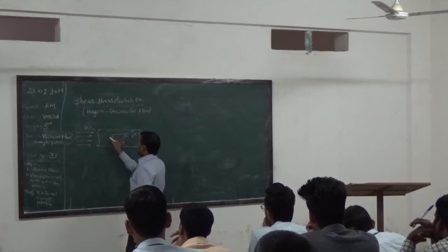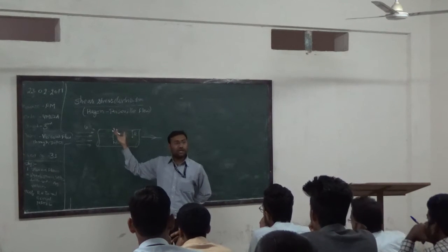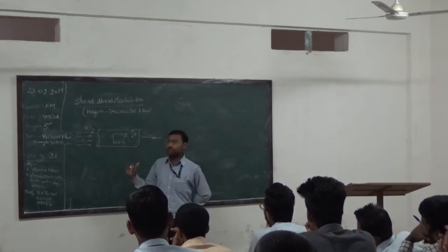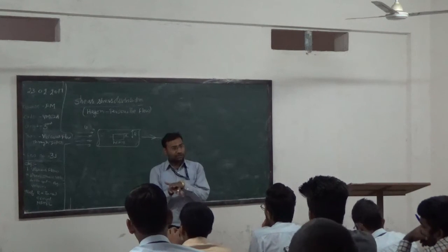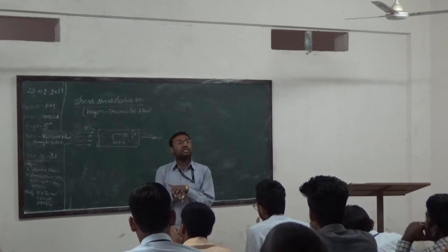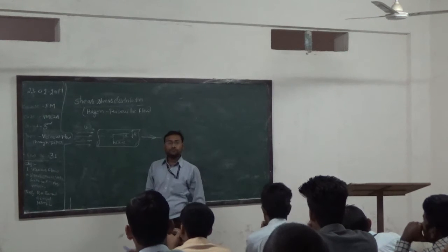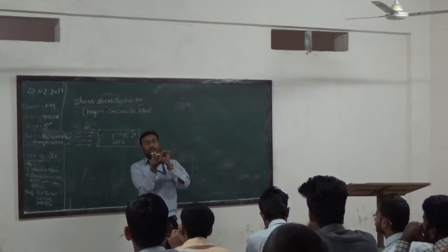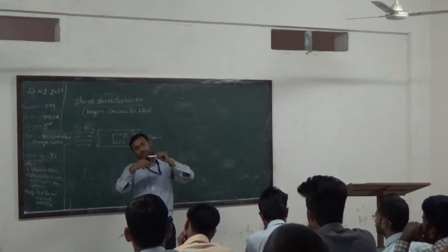Now, as we have already assumed, it is viscous flow. Viscous forces are dominant, meaning resistance will be there. Due to this resistance, shear stress will be developed. In the very first unit, we discussed that due to viscosity, shear stresses are developed in the fluid. So there will be a shear force on this circular element, with shear stress developed over the complete surface.